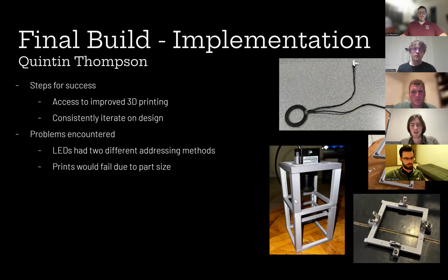As for the implementation, the lighting assembly at the top includes the light ring, the LED ring, which situates around the camera, and the individual lighting sources which chain together on the height adjustable light ring. The general form of the structure is also depicted on the right with the main building blocks: the base with press-fit legs, including height adjustment pegs, the printed ring for holding the individual light sources, and the camera mount, which attaches seamlessly to the base.